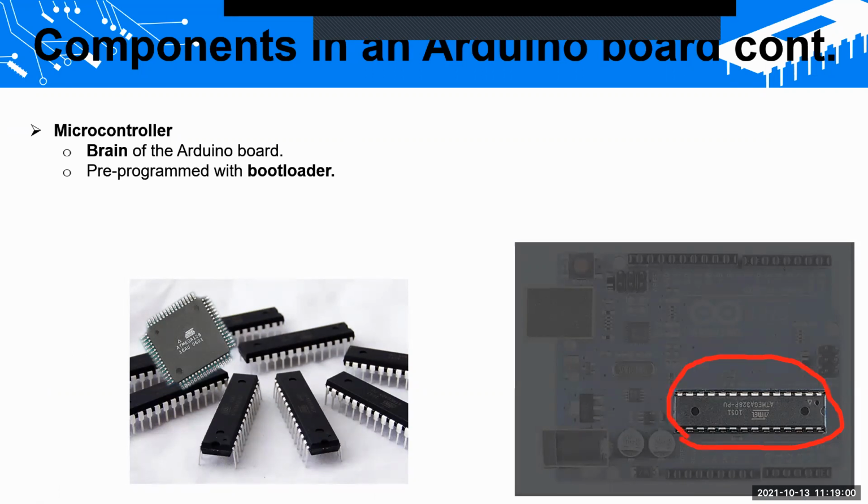It has a bootloader, right? So if you have that bootloader, then you can simply plug this microcontroller into your Arduino board. Then you can plug the Arduino board into your laptop. Then you can easily program the microcontroller, right? So you have to get that idea: this Arduino is only giving the interfaces, right?